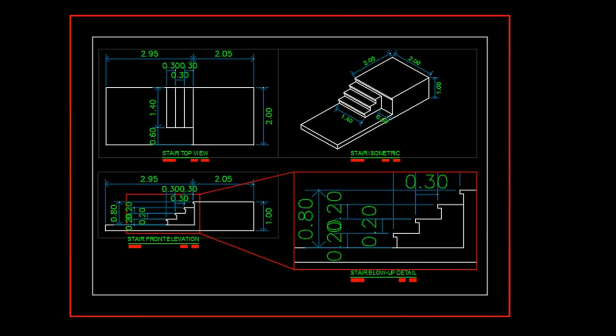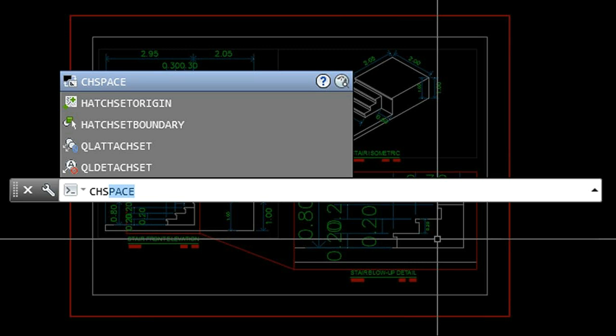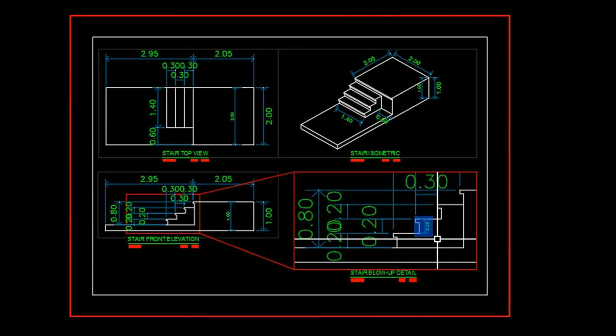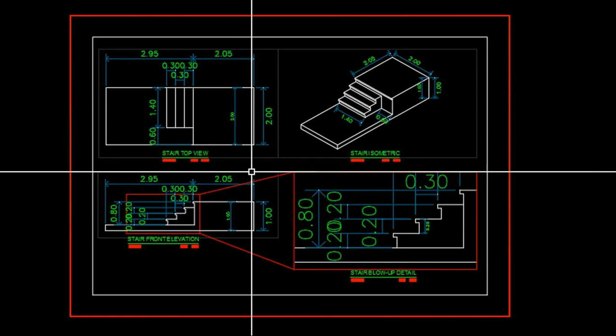Moving on. As you can see, in different scales the text varies on the Layout tab. To uniform the dimension, you can use annotative, but it will be in another lesson. For now I will only show how to uniform the text manually. First you have to dimension the drawing from the Layout tab once in every M view. Then move the cursor inside the M view, then click outside the M view. Then type CH space. Then select objects such as our dimension. Then enter. Then do this to all M views.